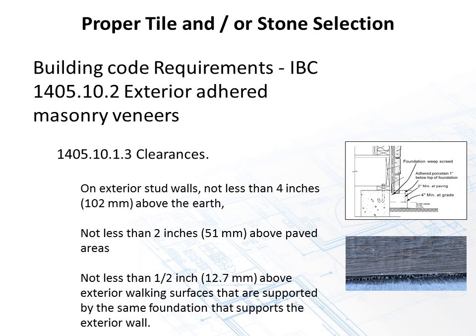Above that, you can see in this detail that we've got cement board. They've got a weep so that water can weep back out, and the tile, or in this case a stone installation, but same principle.